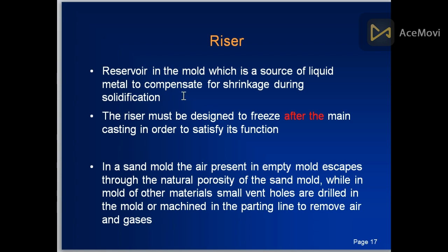There is a riser. It is basically a reservoir, a tank that provides metal when there is a need in the cavity, and it is made in a way that it solidifies later. The riser must be designed to freeze after the main casting in order to satisfy its function.